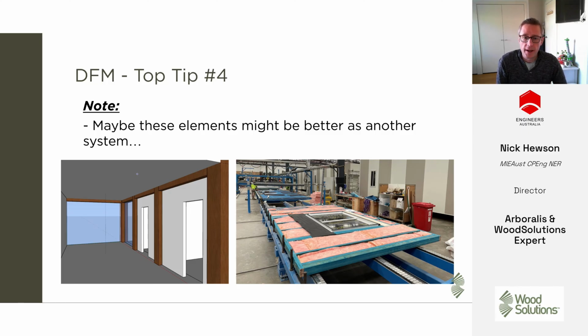But having a look at that last example, there are other opportunities to potentially not use CLT in those examples, whether you could use glulam post and beam or lightweight timber framing, so that you're actually utilizing the timber fiber where it's most effective. It's always something I look at when I'm considering timber buildings.